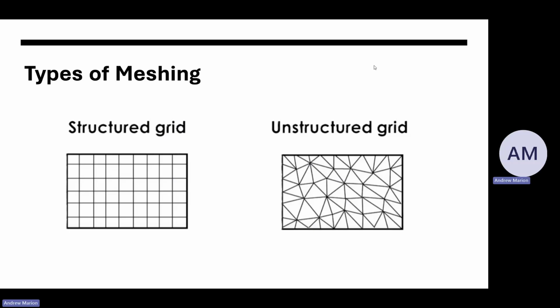Mesh controls that you can use to make an unstructured mesh a little bit cleaner. Beyond that, there is structured grid, where everything is a perfect cube or at least some sort of rectangular prism. Sometimes they're a little longer than others. The absolutely ideal would be to have everything be a complete structured grid. That is not always possible, though.